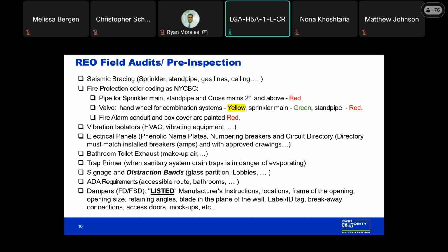We should know that there's a static inspection, so making sure we have the proper annular space. We call our quality assurance division partners to come out there and review that static installation before we install the angles and continue with the installation of the fire smoke dampers.